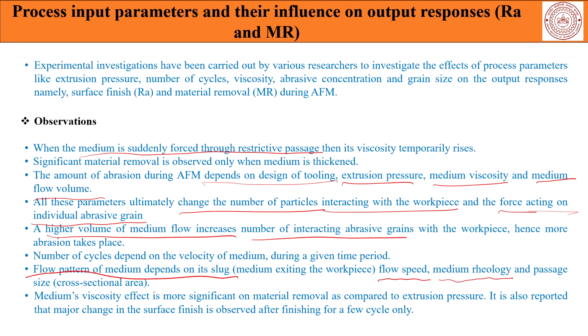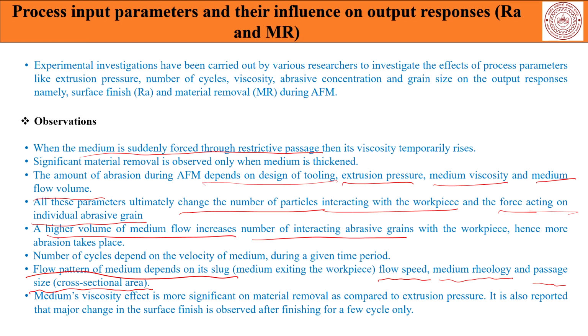Again, the medium rheology after passing through such small crevices and passage sizes, and if you stress the fluid more, it is obvious that the overall internal energy would increase, because then it has to go through severe interlayer stresses as it goes through smaller and smaller channels. So, the medium's viscosity effect is kind of the most significant property which determines the metal removal, and perhaps it is a dominating factor